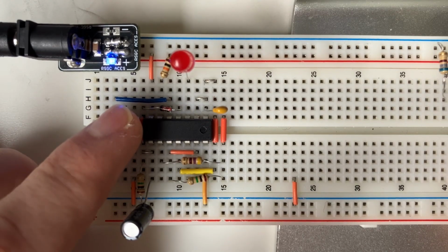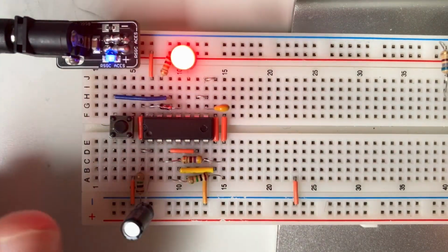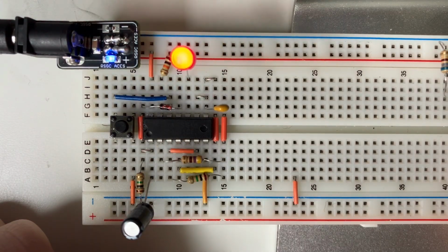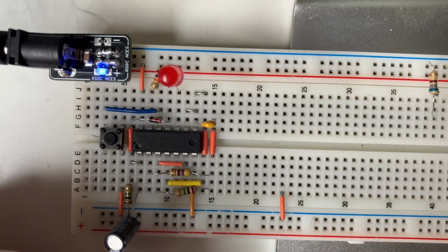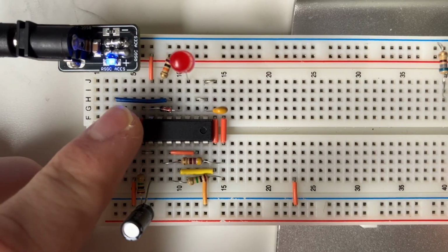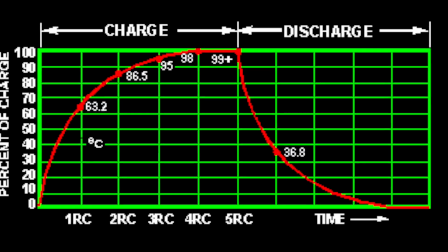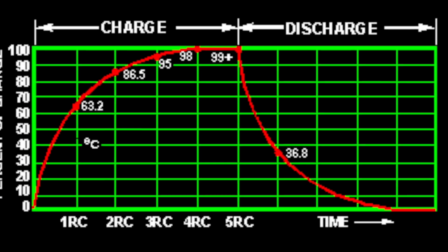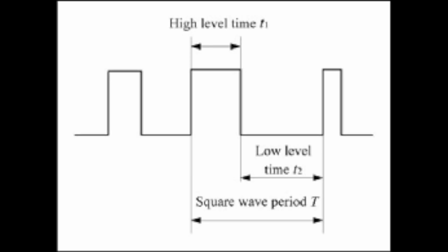The next key factor to understanding the counting circuit is the NAND gate oscillator. The NAND gate oscillator provides the clock signal for the ultimate counting circuit. This clock signal is provided by the charging and discharging of the capacitors, which can vary depending on resistance. This charging and discharging creates a square wave, which ultimately sets up the base for the counting circuit.